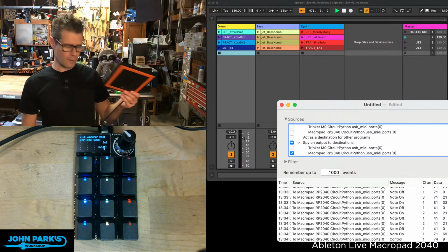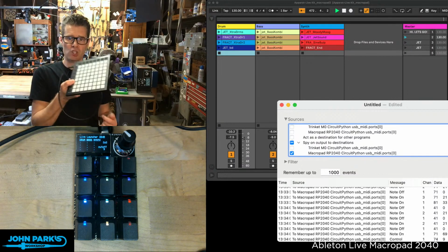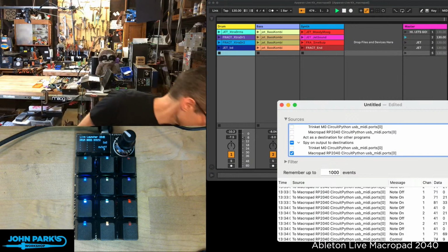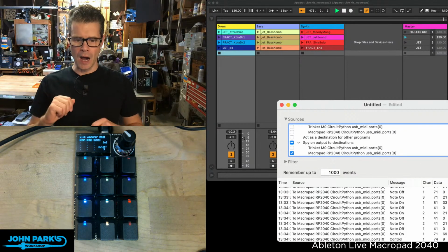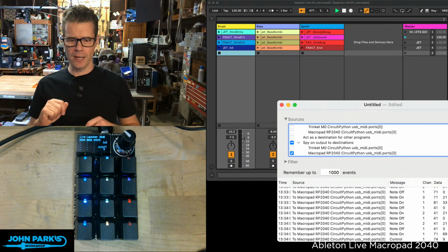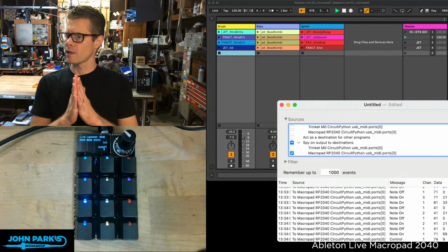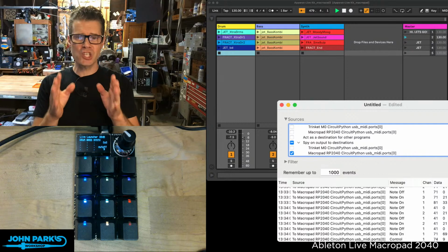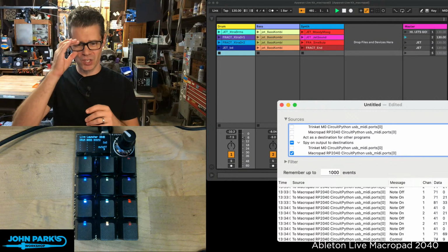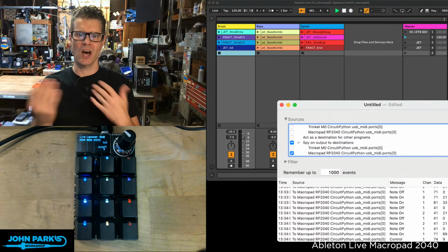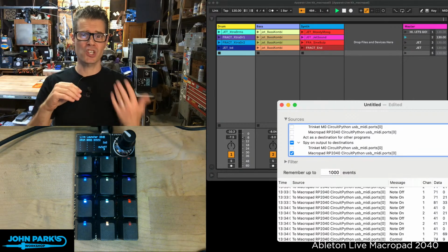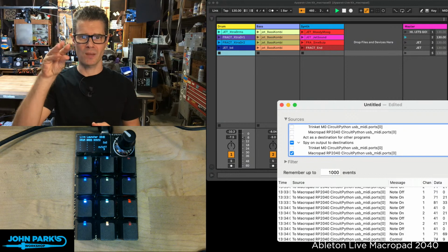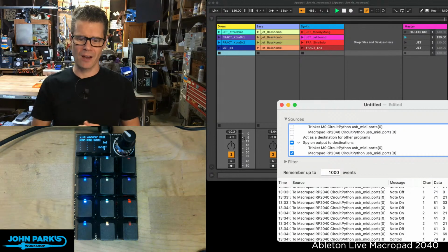If you look in the developer's guide, or if you have one and you spy on the traffic, what you learn is they use 3 MIDI channels, 1, 2, and 3, to mean different animation states of the LEDs. Sending something on channel 1 is on and off. Sending something on channel 2, I think, is a blink. Sending something on channel 3 is a breathing, like a soft fade up, fade down.